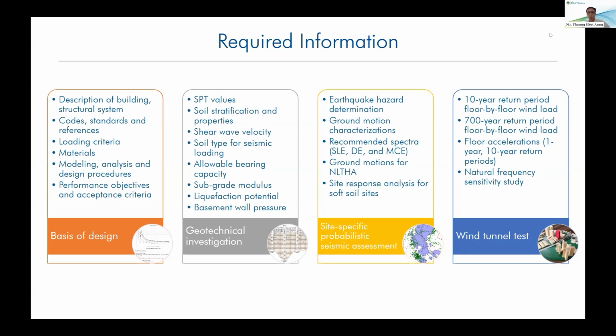And the third one is the site-specific seismic hazard assessment. That part is additional to the normal code-based design. We have to carry out the site-specific assessment for the seismic input. That consultant provides us the different response spectra for different levels of earthquake, normally service level earthquake, design earthquake, and maximum considered earthquake. For the maximum considered earthquake, they provide the ground motions to be used in the nonlinear time history analysis. If the building is located on soft soil, they also carry out site response analysis to check the amplification of the ground motions due to soft soil.